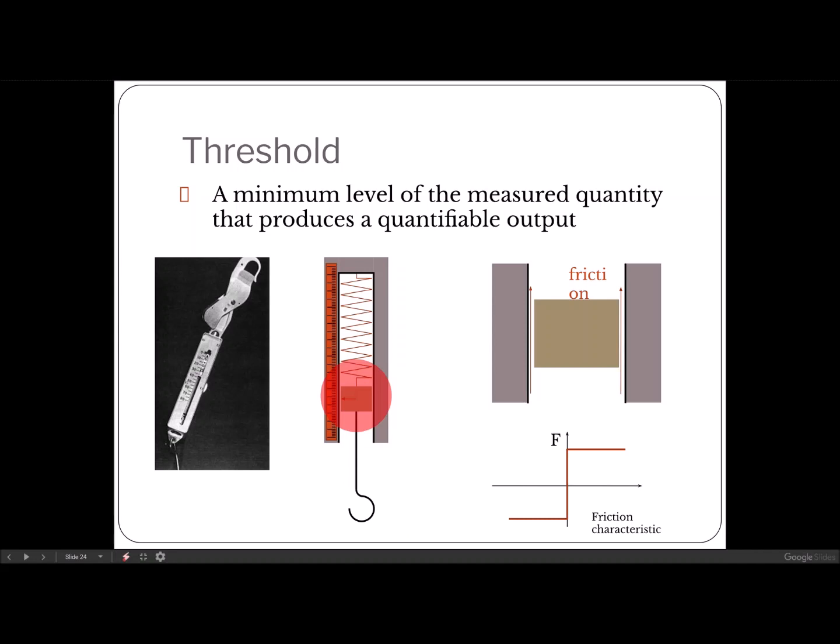So technically what it measures is the weight of your suitcase, but how it measures, what is the output of this weighing scale? It's basically deflection. So if you look at this weighing scale, it is equipped with a spring with a known stiffness. So when you know the stiffness, you know the deflection, then you can estimate the force. Basically it's just like that, right?